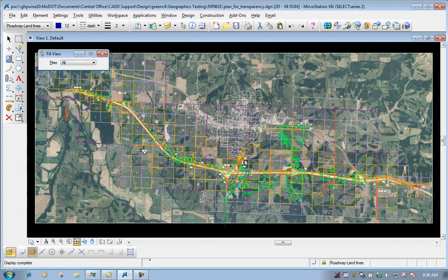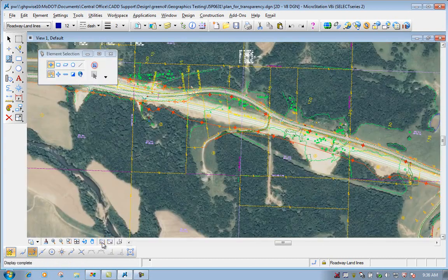Like I said, I'm just going to copy this information over here, outside, because whenever I try to place those transparent fills, if I zoom back into the area and try to apply that transparent fill right now using the create region tool, which we will use later on, it won't fill it correctly because we have other geometry that's inside here.